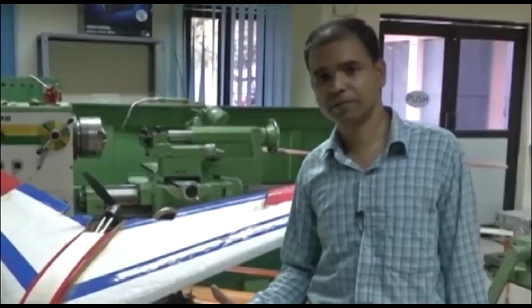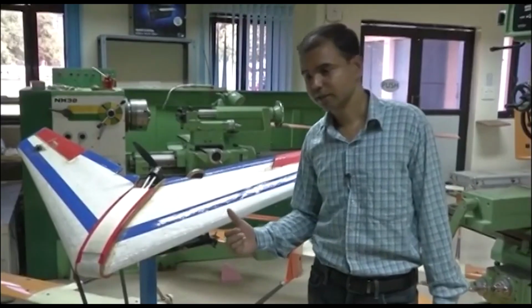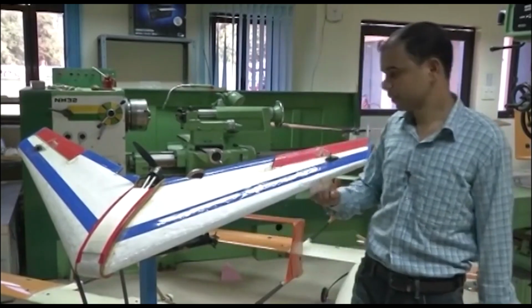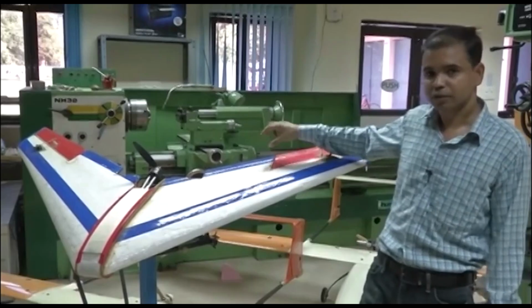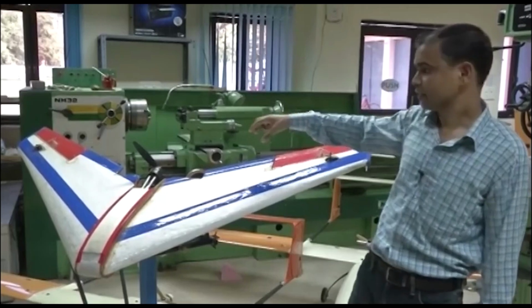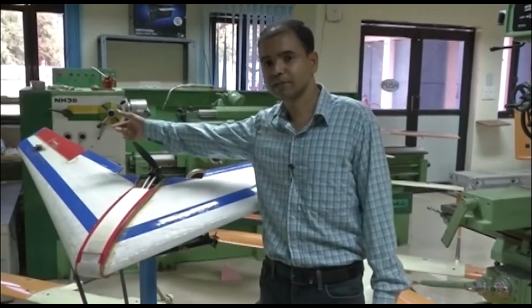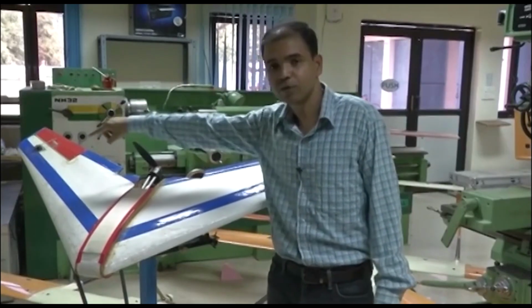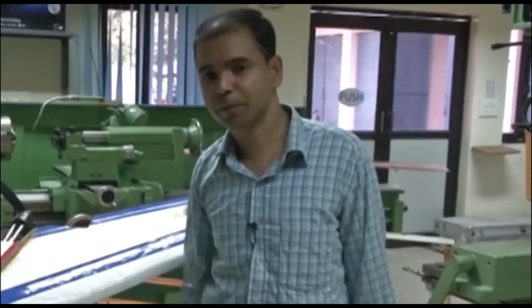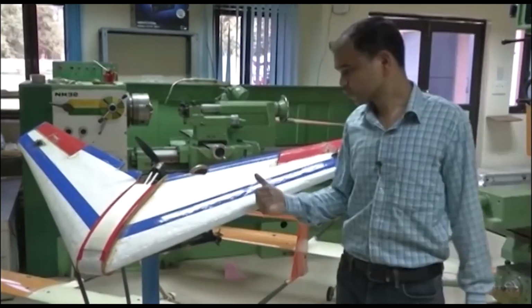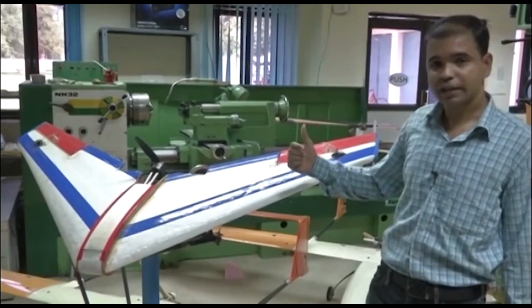Because we are using a common surface for both aileron and elevator, suppose I am giving a climb with a right turn, so what will happen? I will give symmetrical deflection for the climb, and because I am taking a right turn, I will reduce left aileron deflection and I will increase the right aileron deflection. So what happens? The right aileron deflection will become very high, and that will enter into the non-linear region. Designing of control becomes complicated because we need to handle that non-linearity which has arisen because of the deflection entering the non-linear region.